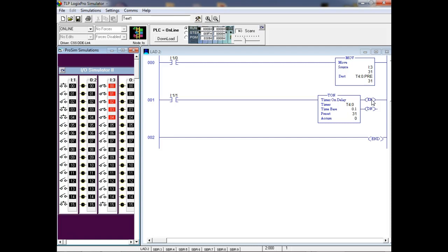I remember that now. And also counters. So C5, the first counter would be C5:0. And the next one I use is probably 1, 2, all the way to 255, if your PLC supports it. We ain't gonna go that high. No, we'll never go that high, but you don't have to start with 0.